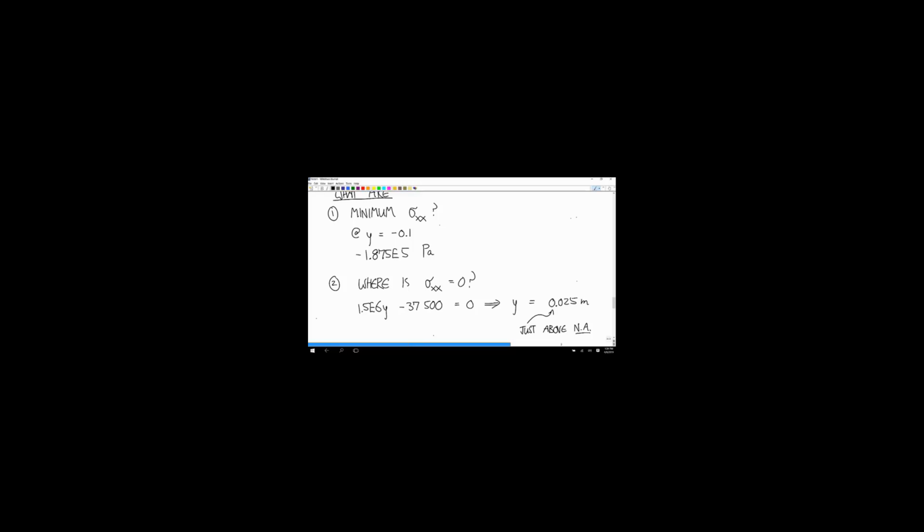But there are cases where, if you want to control the stress due to bending, you know, you're worried about the stress due to bending being too big for this thing, you can apply tensile or compressive stresses that offset that bending moment at a certain place. That's called preloading, and you can sometimes use that to make your thing stronger in the application it's used for.